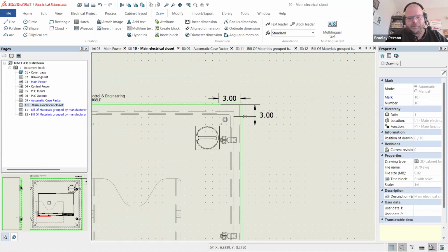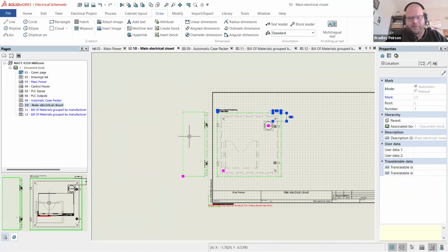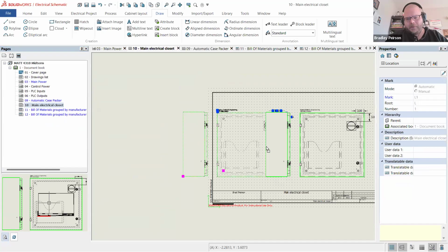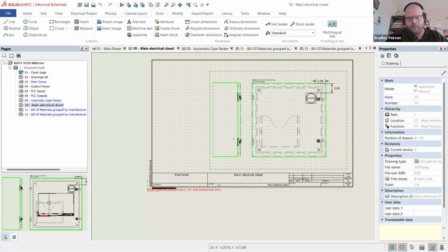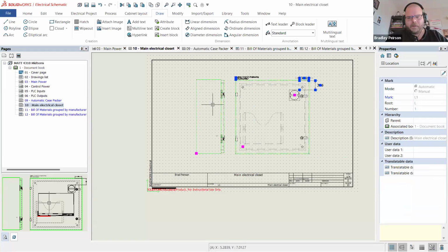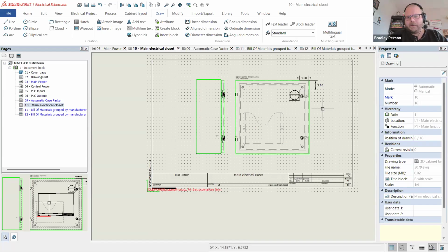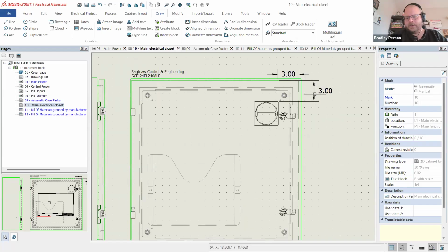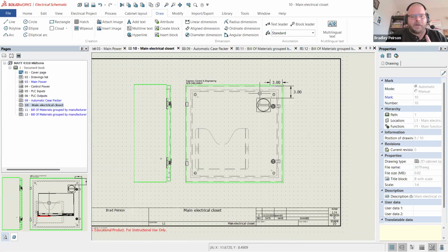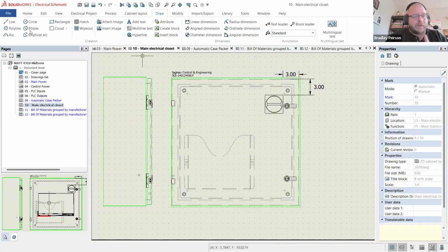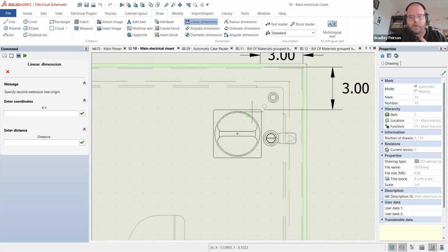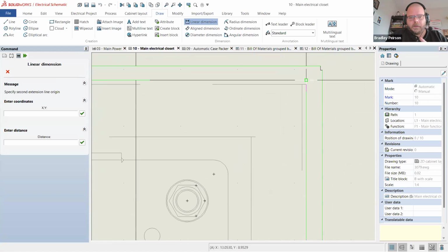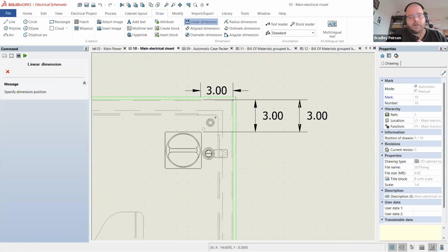It's like old school AutoCAD rules. Once the dimensions are in there, they are just drawing objects. They are not going to update intelligently. So scaling did not change the fact that it thinks those are 3 inches because they're kind of dumb once they're in. The reason I recommend doing it in 1-to-1 is if I were to dimension it now, let's do a linear dimension, from that corner to this corner, oh, it actually did scale. SolidWorks fixed it.